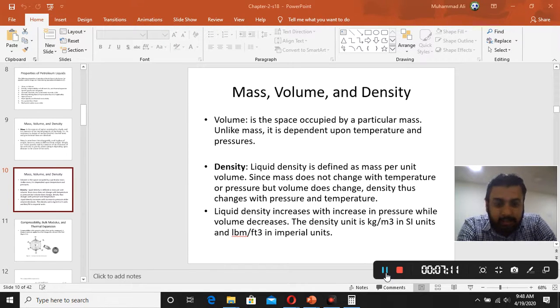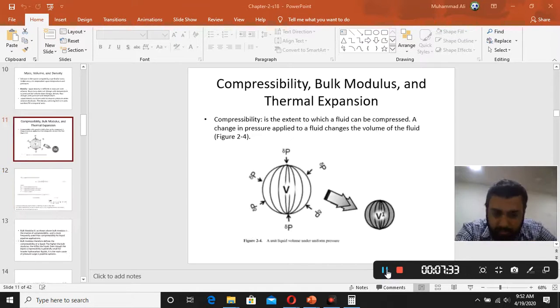At the same time, volume changes because of the temperature effect. And if the volume of the oil in the pipeline changes, it ultimately changes the pressure of the system. Therefore, we have to be careful about the pressure in the pipeline. If there are pressure fluctuations because of the volume changes and temperature changes, we have to consider that.